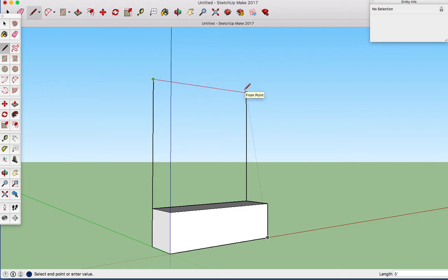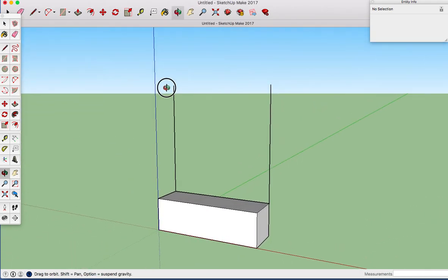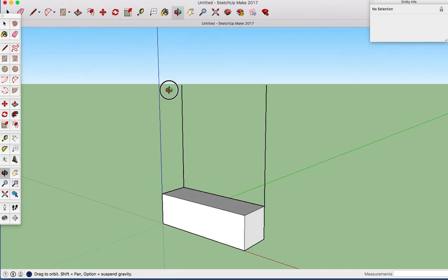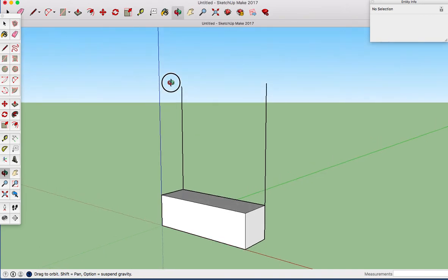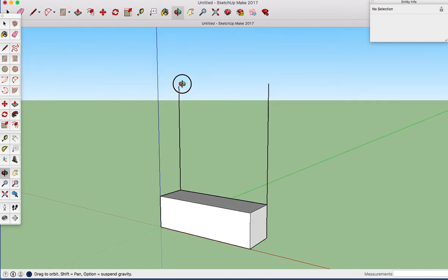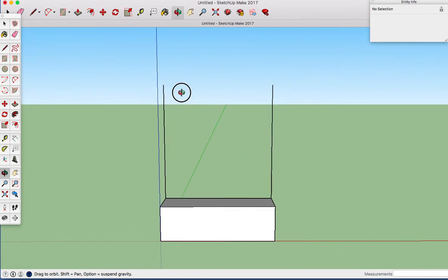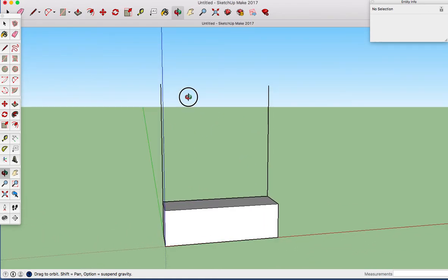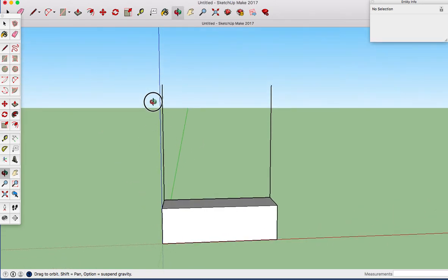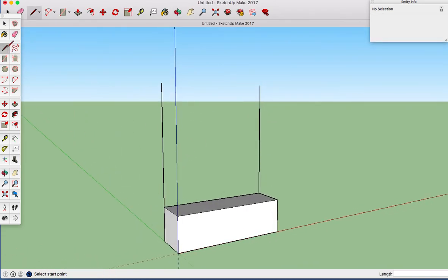So now when I connect these 2 points, I just hit the escape button. Anytime you hit the escape button, that releases the holder that is looking for the next point. So if you made a mistake and started from the wrong origin point, you can just hit Command Z or hit escape. But I've got two lines going up at 80 inches.